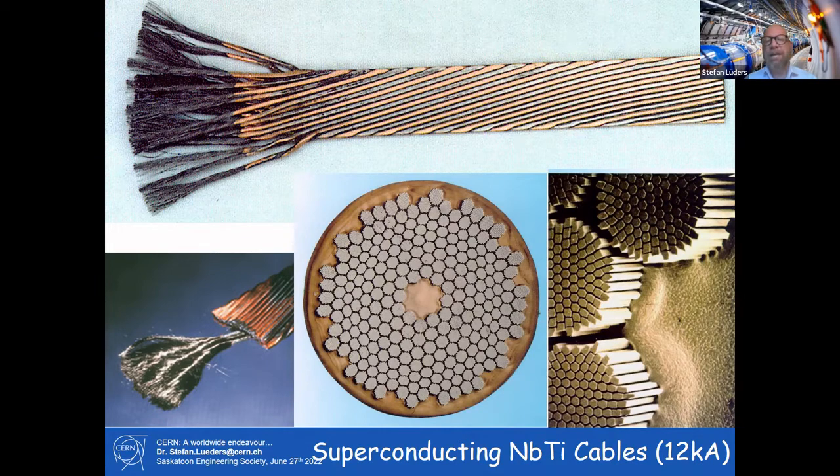So the first turn we need is detecting that something is wrong. We need to dump the beam. Voltage is not nominal anymore, temperature is not nominal anymore. One turn to detect this. Safety systems are all laid out so that they just need one turn. The second turn we need to transfer the signal to dump the beam from wherever it's detected to the single point in the LHC where the beam dump is. Remember point number 6?